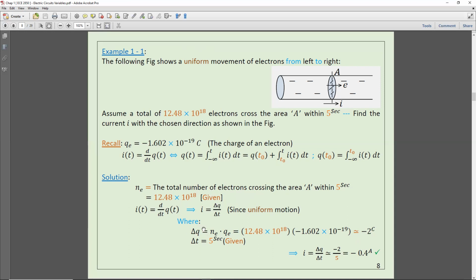And so here we have constant change. So every 5 seconds, the change here in Q is 2 every 5 seconds. So that's why when you calculate I here, I is actually the change in Q divided by the change in T, and this is constant, okay? So it should be -2 divided by 5, which is -0.4 ampere, okay? Because the unit of current is ampere, okay?